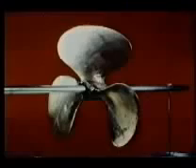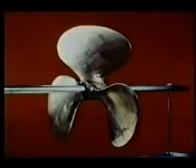This propeller operated under cavitating conditions for only a few days. Similar damage can be produced on pump parts, such as this impeller of a pump for high-temperature liquid sodium, and in the low-pressure regions of hydraulic structures, such as this large power dam spillway tunnel. There has even been speculation that brain damage can be produced by the collapse of bubbles in the cranial fluid when the skull is accelerated under the action of a sharp blow.